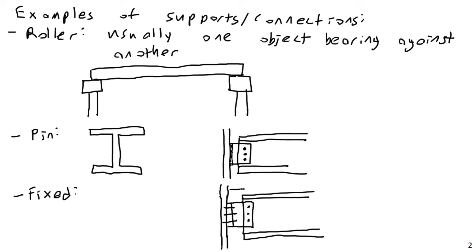Then I would need something up here, some flange plates, to mobilize the flanges and give me some moment capacity as well. Not to scale. Maybe have a fillet weld here, some sort of fillet weld up here. But anyway, the whole idea is that I'm going to be doing something to connect up the flanges in addition to the web.